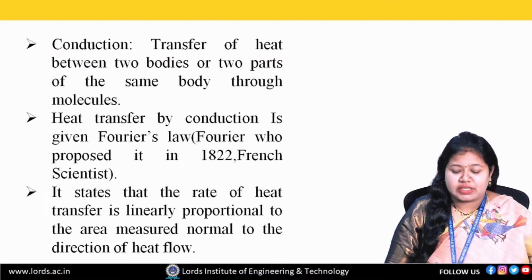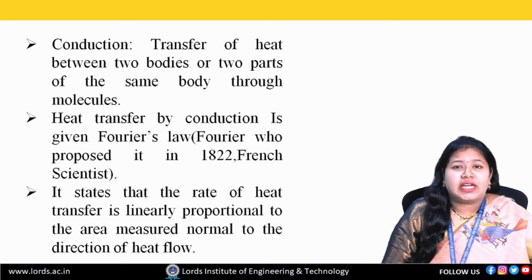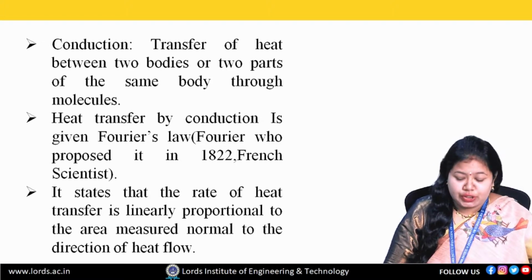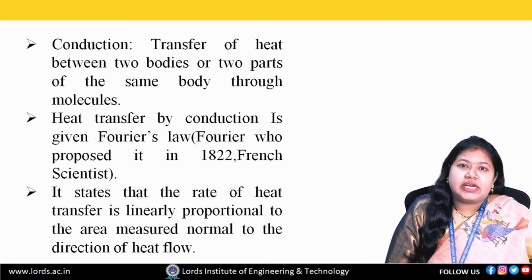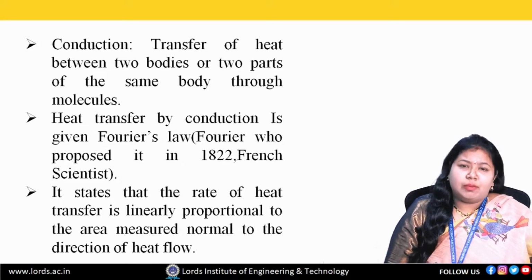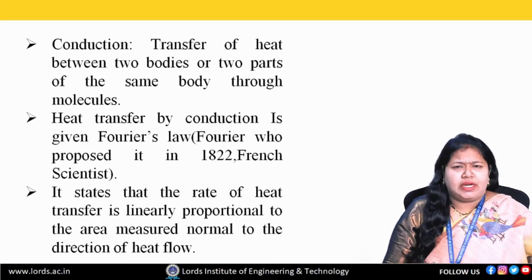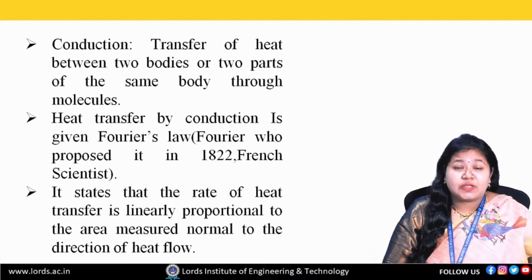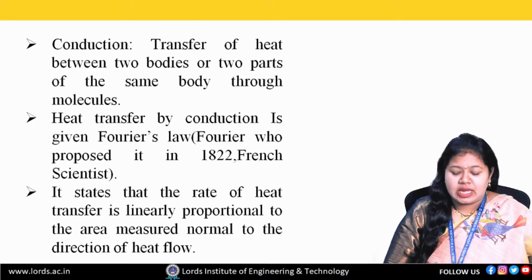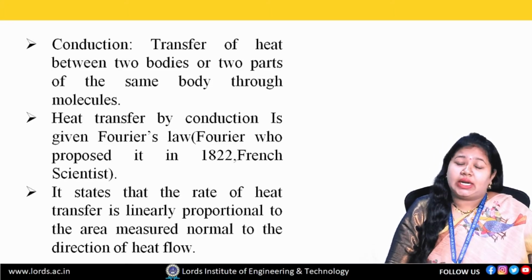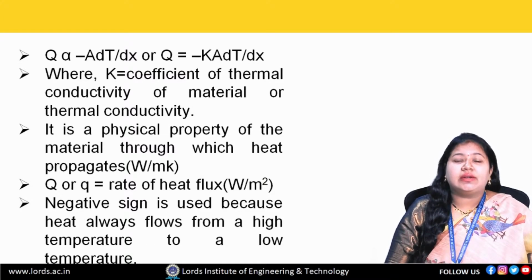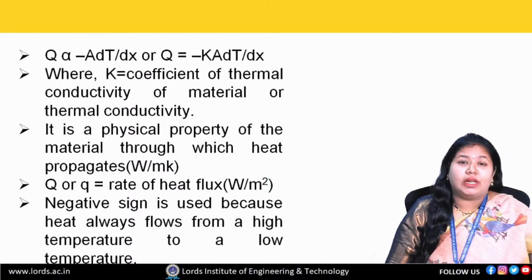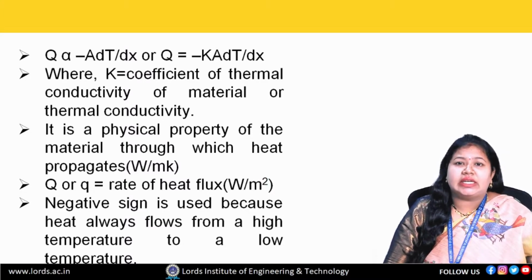Conduction was studied by Fourier, a French scientist, in the year 1822. The same principle applies here also. It is the transfer of heat from one body to another body or from one part to another part, but it takes place only within solid bodies. Here we are going to find the heat flow rate. This heat flow rate can be found using the formula Q is equal to minus K dT by dx.